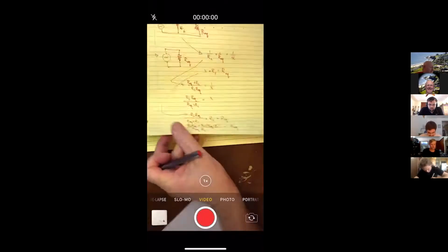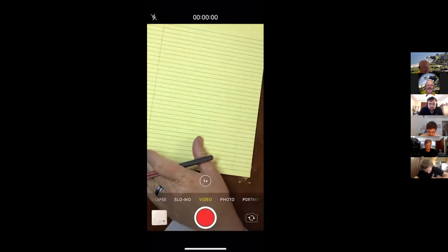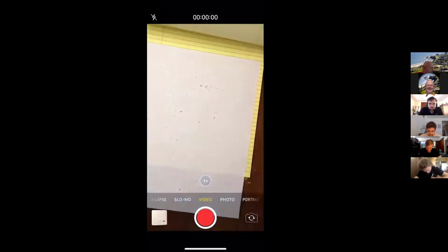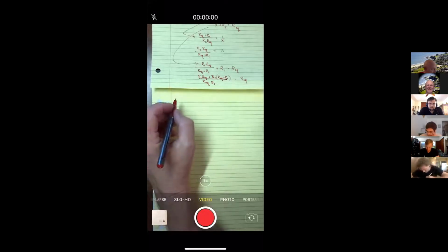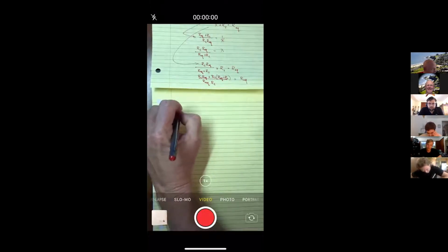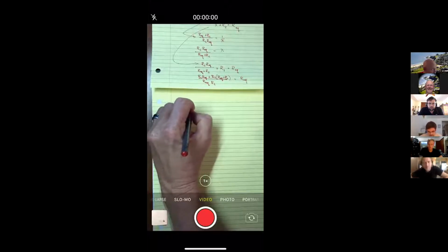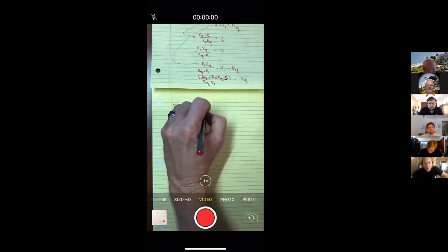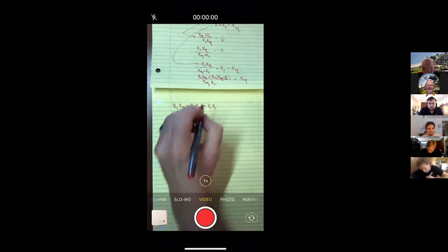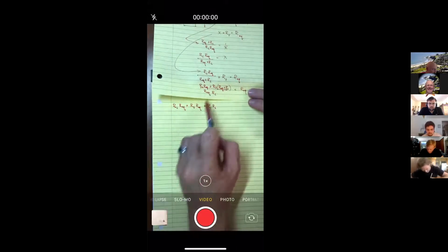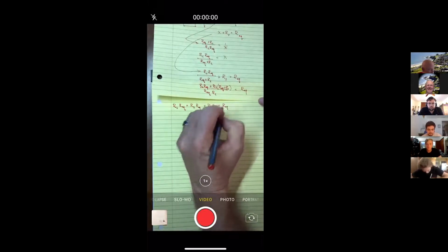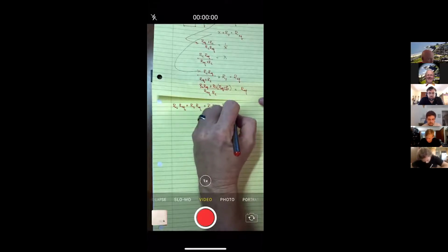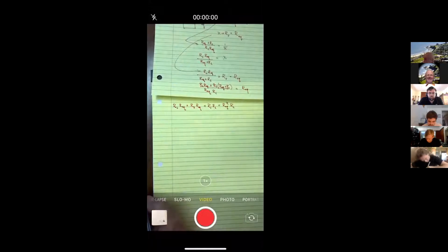Now, I've got some more math to do. Let's see, bring this back into the picture here. I'll just write the numerator: R load, R equivalent plus R transmit, R equivalent plus R transmit, R load. So that's what I get in the numerator when I leave that alone and do the distributive property. And if I bring this to the other side, I get R equivalent squared times R load. And I would like to solve this for R equivalent.